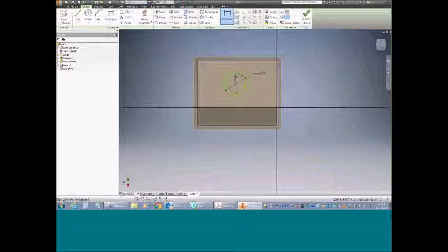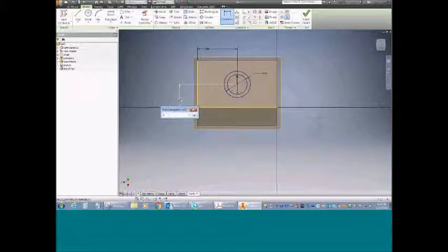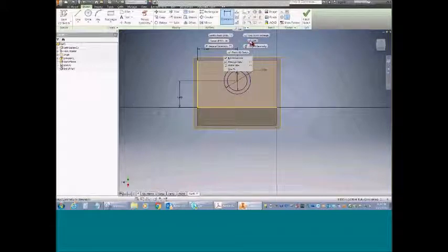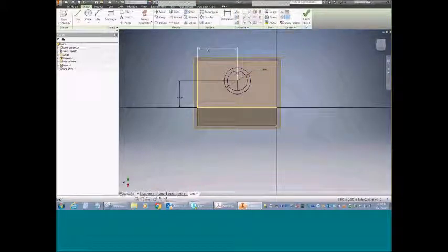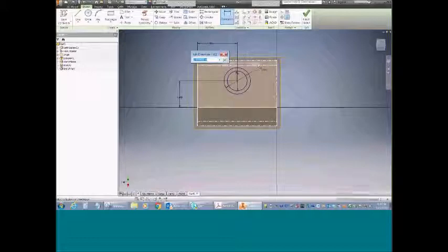Need some placements here. That should be 1.5 inches. That should be 1 inch. So for this 1.5 inches, we can put in that dimension. We can do the math in our head. This was 3 inches across, or I can simply add this dimension, and I would encourage them to do this, is to go in and use the show dimension.